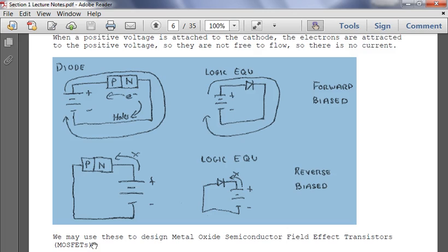As a potential topic for a semi-weekly discussion, forward biasing and reverse biasing in CMOS is actually used as a method to either reduce power consumption in the case of reverse biasing, or, with forward biasing, improve what's known as rise time. So you can actually talk to them about how forward biasing or reverse biasing impacts circuit operation.